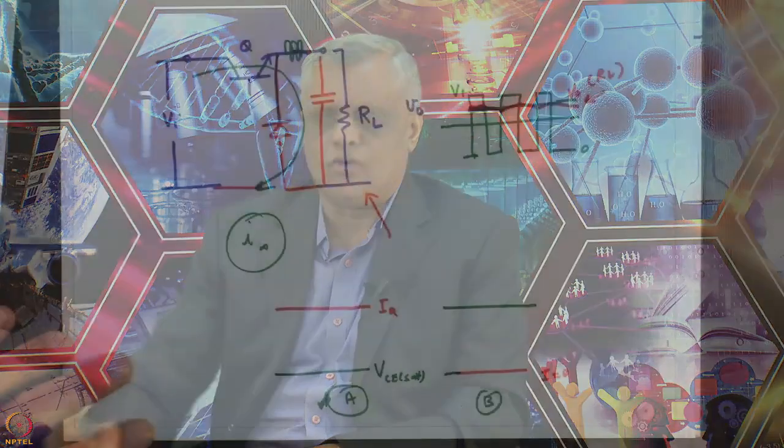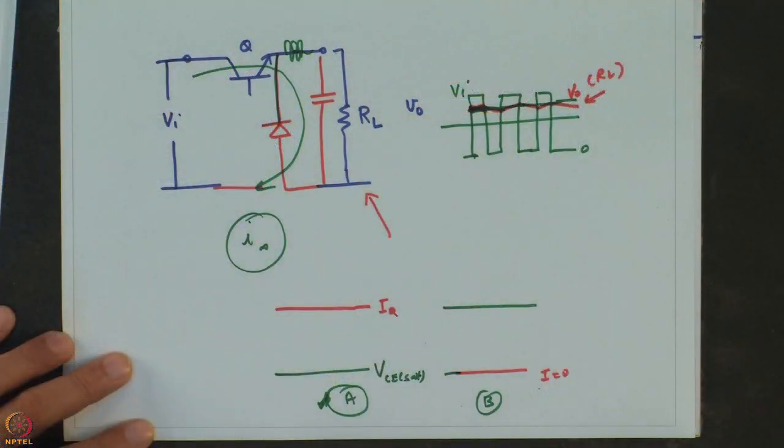In the switch mode regulators this is not the case, and it is a direct result of using the device Q in the on off mode. Of course, the price we have to pay is a non-linear control, more complicated than the linear regulators, and the use of filters, which require additional components like the diode to appear in the circuit.